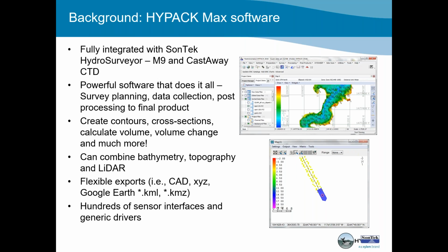We can create contours, cross sections, calculate your volumes if you are surveying a reservoir. You can do volume changes over time and many more features. I can't show you everything because HYPACK is a very, very powerful tool. We not only do the SonTek Hydro Surveyor, we have more than 400 different sensors, and you can combine them all.